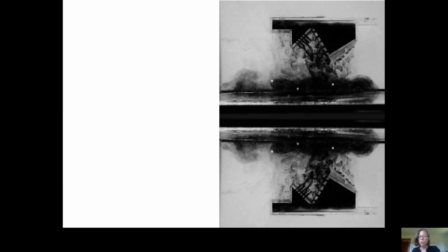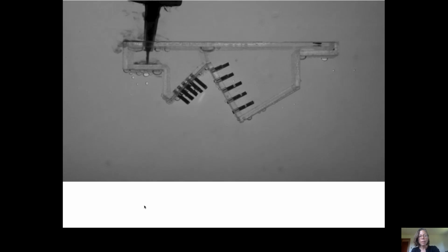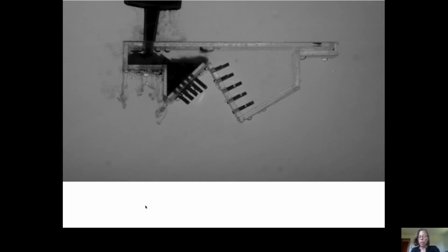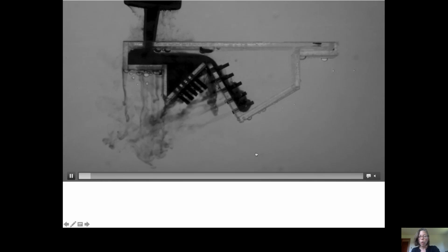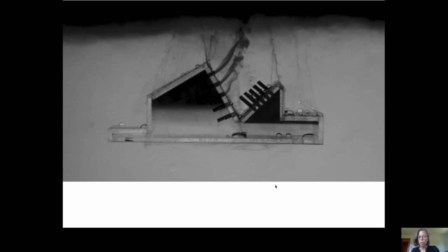The third technique that we used were called filling tanks. This is a mechanical engineering technique that makes buoyancy-induced airflow visible. The way that technique works is that salt water is introduced into a plexiglass model submerged within an aquarium, and this enables visualization of either the introduction of cold air into a warmer environment, or, when the model image is flipped, the introduction of warm air into a colder environment.